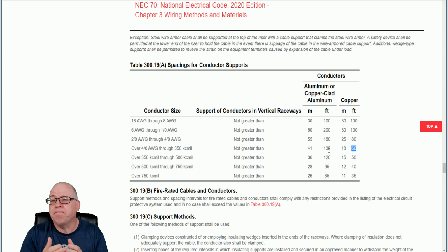And to be honest with you, it replicates a solid conductor. Now, as far as ampacity goes, aluminum's obviously got to be bigger than copper to carry the same relative amount of current. But now that it's all compact, most of us in the industry make only compact conductors for aluminum. What you're going to find is the size difference is not so big anymore. So it can be a benefit.